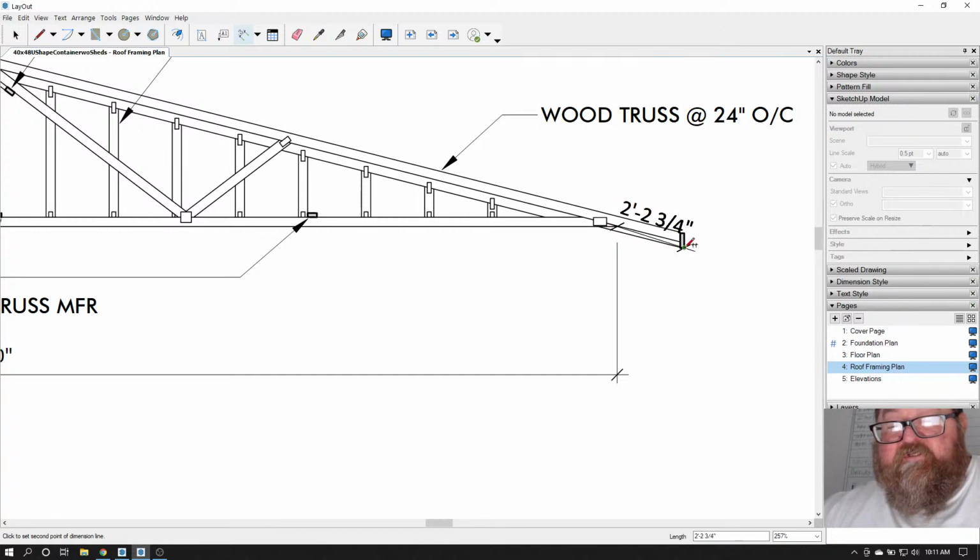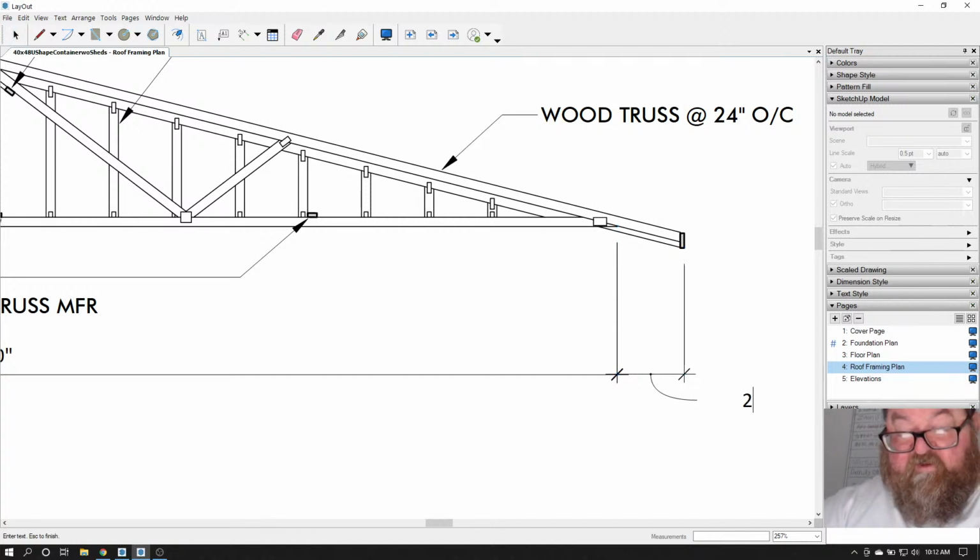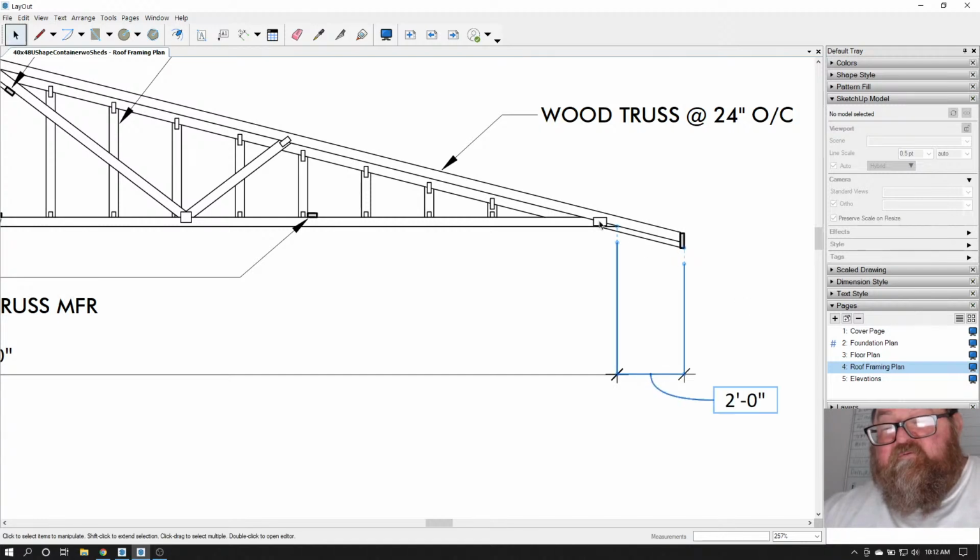Well, the roof extension makes the truss tails. When you're ordering your trusses, you need to tell your manufacturer that you only want that tail 22.5 inches, because if you don't, this will happen. Your soffit will be too wide to use 2 foot wide material, and that's a tragedy because you'll be wasting a whole sheet.